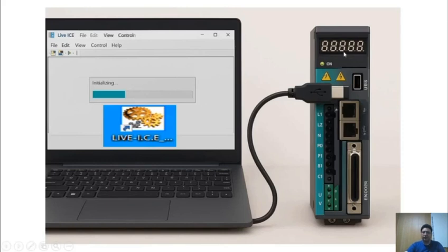After we have securely connected the necessary connectors to the servo motor, for our servo drive we need to make a series of important settings. For example, we need to specify the unique motor ID, or the exact type of motor encoder, whether it is absolute or incremental. We also have to set the encoder resolution for the drive, along with any other necessary configuration settings.